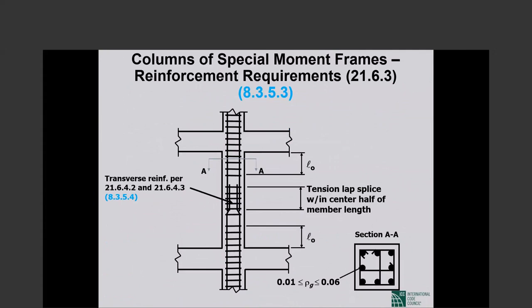Okay, longitudinal reinforcement in columns. Minimum 1%, maximum 6%. The minimum 1%, I am sure I discussed in concrete design, becomes 0.5% because of the limitation: you can go with 1% of the required section, not the section provided, when the column is larger than required, which it always is in the upper portions of a multi-story building.